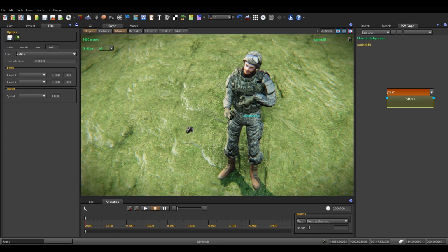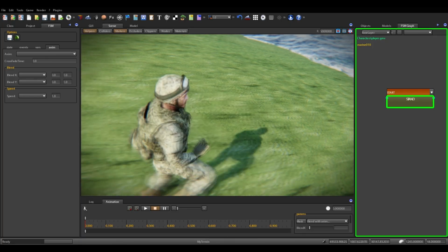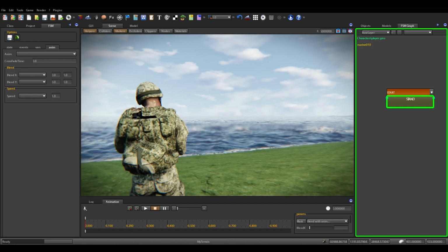Now we can make the character animation we have just created before blend basing on the character speed from standby to run. We take care to make the maximum blend x value match the defined character speed, in our case 300.